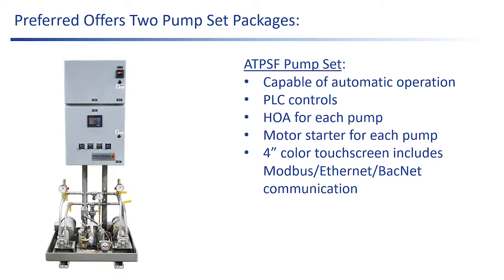We can also throw a tank gauge into this so that we do the level sensing and leak detection in the main tank. If you've got containment piping, the leak detectors can be wired into this PLC or into the tank gauge. So even though it's not strictly required, more often than not, we end up providing this style of pump set even for boiler jobs because of the processor and the color touchscreen.